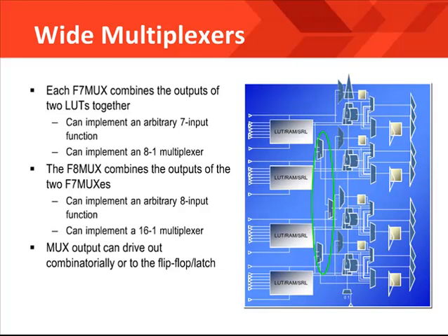What is most important to remember is that each of the dedicated resources has an intended purpose of saving LUTs and improving the speed of the design. And as an FYI, be sure if you're going to code for these muxes that you build them with a proper case statement.